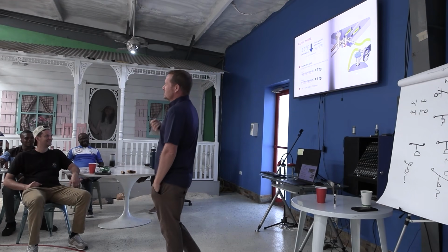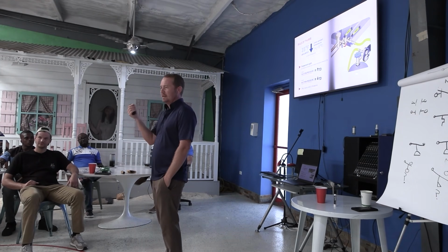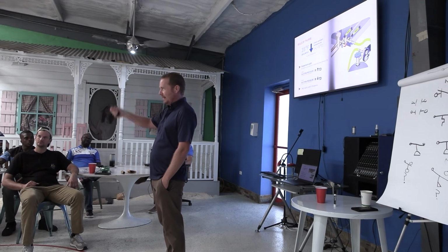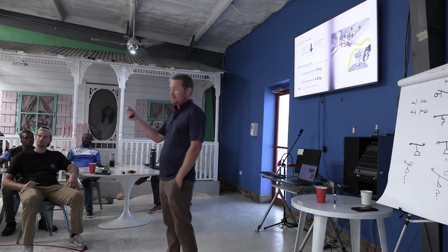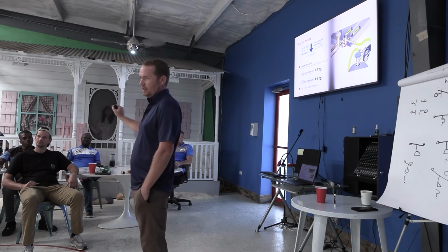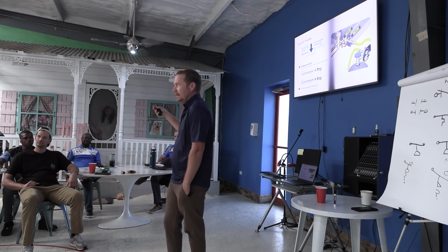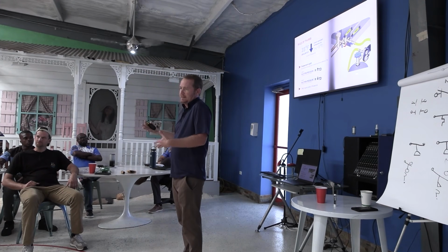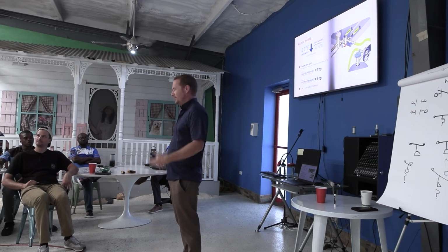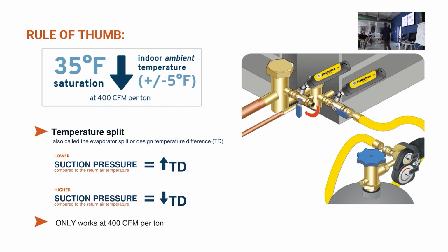It does require some conversations sometimes to help the client understand. It's not what you set it to that's the problem. It's that it will freeze once it gets to a certain temperature inside your home because of how all air conditioners, residential air conditioners, are designed, right? You could design a system that didn't freeze, but it would then not dehumidify well. There would be this whole issue there. So understanding this is really important. Does that make sense to everybody?